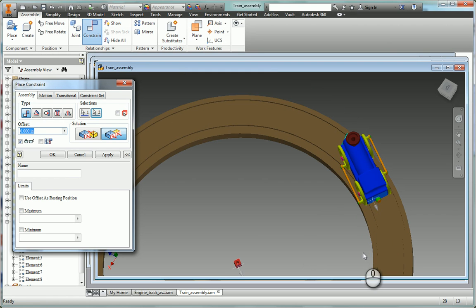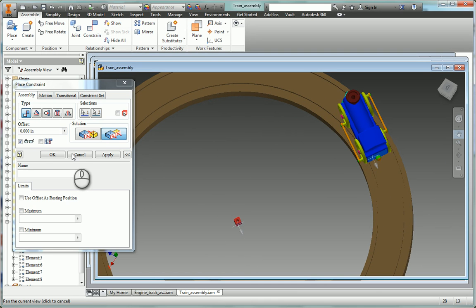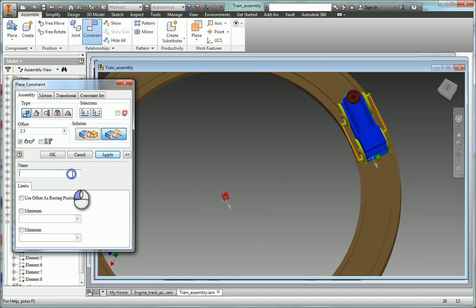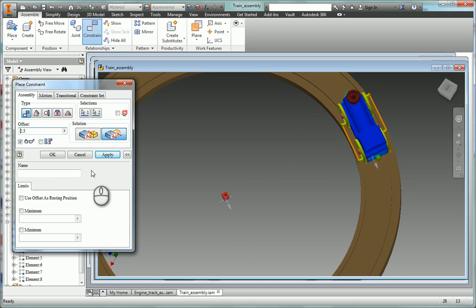And that one there. You'll notice that didn't look like it helped very much. It looks like it's a lot more off. But I can, again, offset this flush. So these don't have to be in a perfectly straight line. I can offset one of them with the other one. The offset for this flush is like 2.5. That makes it better. It might end up being too far back this way, it could be either way, and then you might have to go negative 2.5. But clearly, negative 2.5 isn't the way I need to go with mine. So 2.5 will work, and I'll apply that.